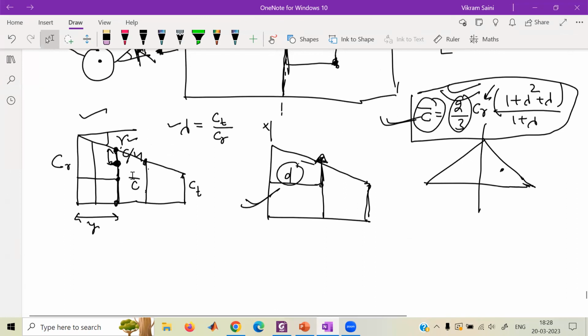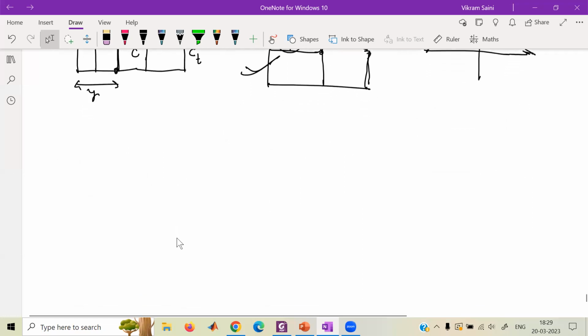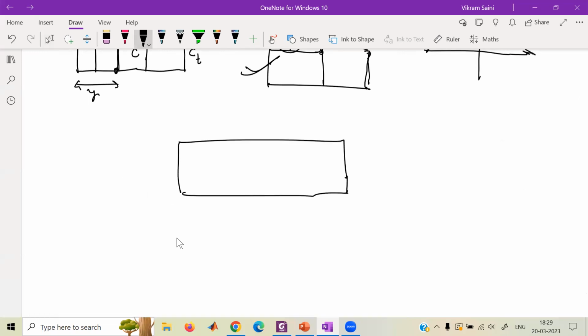And corresponding to that C bar, we can find out what is this length y from this vertical line here at the root. Okay. So now I hope it is clear to you that given the geometry of the wing, you can find out a point at which the net lift is acting. All right. So let's call this length some y bar for the time being.